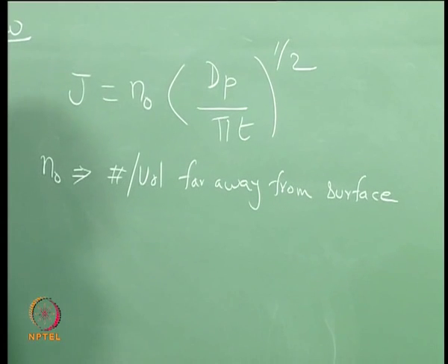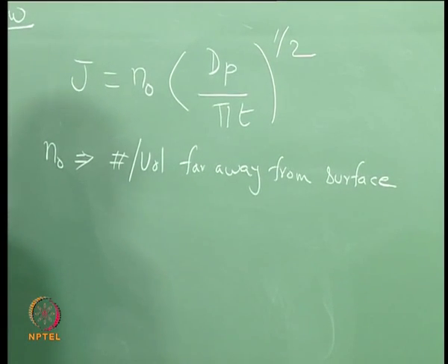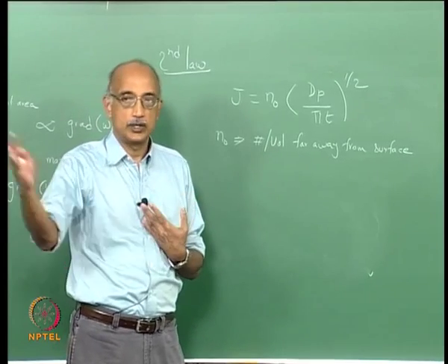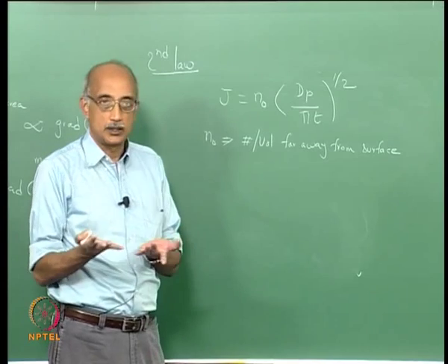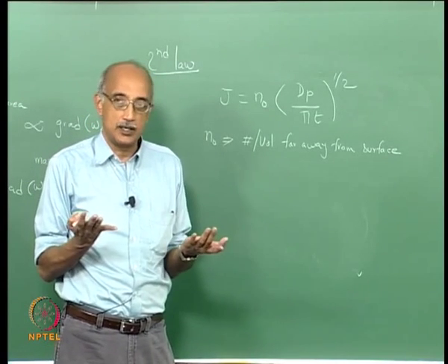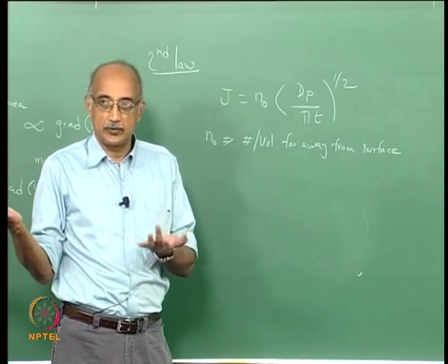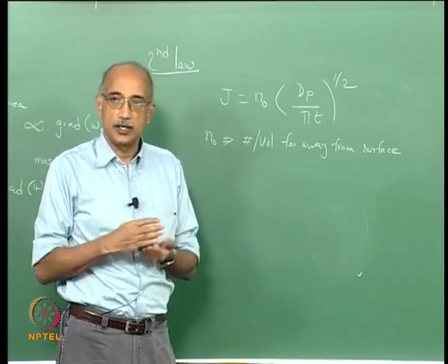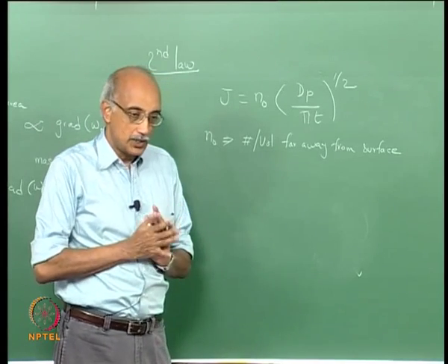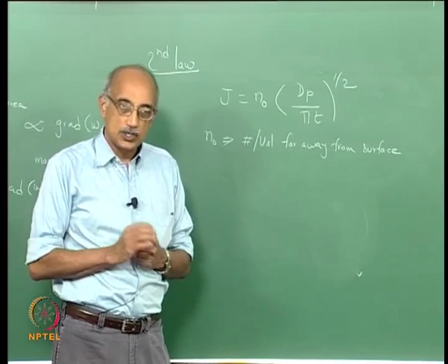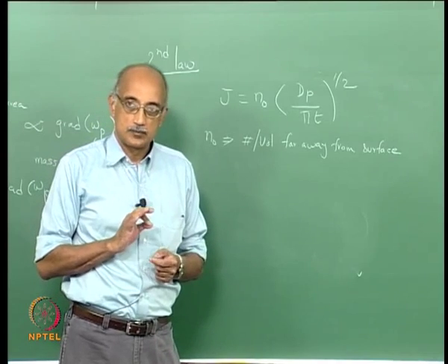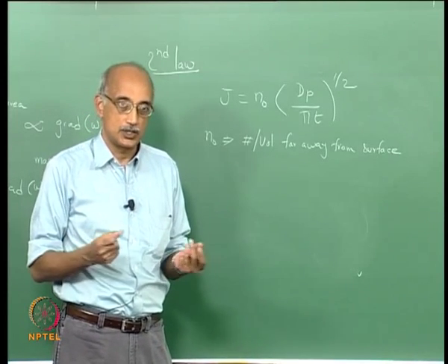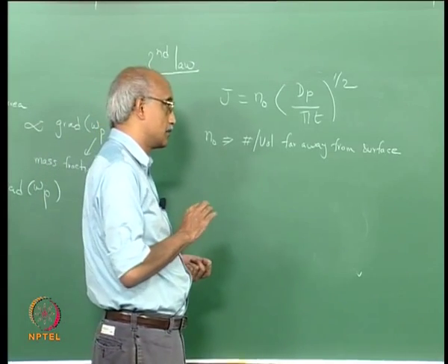By the way, one of the things you have to consider is why does flux even happen? Why does mass diffuse in a certain direction? It's because you establish a gradient in that direction, right? But how does the gradient get established? If you have a free flowing fluid and you are assuming that particle movement is completely random, then in theory there should not be a gradient. Essentially the concentration should be roughly uniform everywhere if concentration distribution is occurring only through diffusion processes. So what leads to a gradient? Well, if you are just looking at the flow of a fluid in a free volume, diffusional phenomena are virtually absent due to concentration gradients alone. Diffusion still happens because of other factors such as thermal gradients or other energy gradients, but not to a significant extent based on a mass gradient.